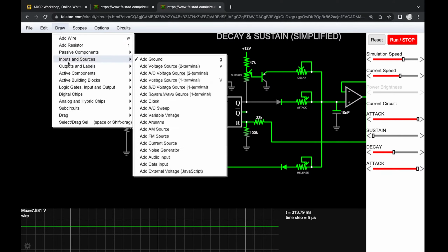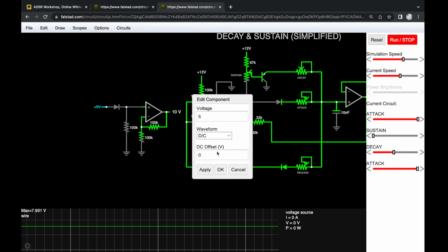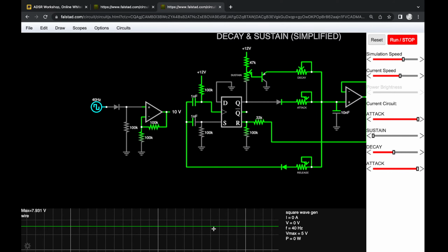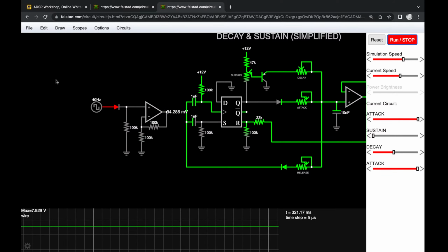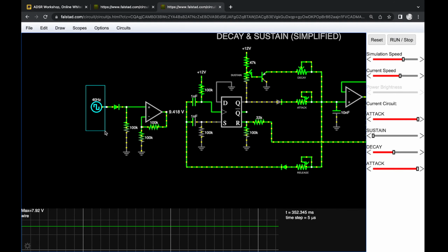And then we are going to set up a little input signal, and we're going to make this a square wave, and this square wave is going to oscillate between 5 and -5 volts, right? Because we want to be prepared for the situation where the input gate does not drop down to ground, but maybe it drops down to a negative voltage, and we want to be prepared for that. So we're going to assume that we have a +5 -5 volts clock here.